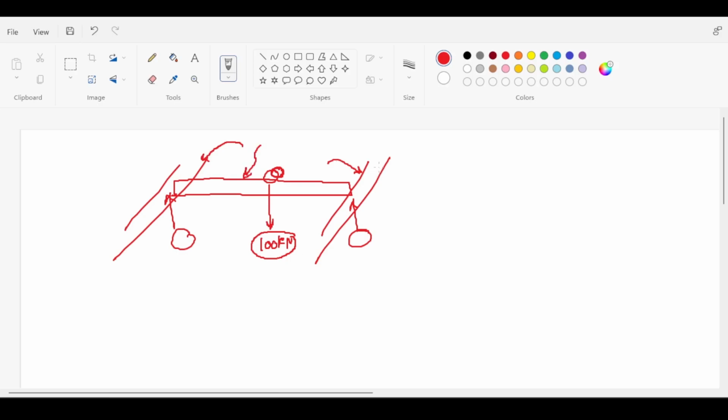Also, from one project I was involved in, the person or the company that is going to come and install the girder will ask you about specifications for the columns as well as this little extension that you put on a column to put a runway on it. Those are also controlled by our crane manufacturer.